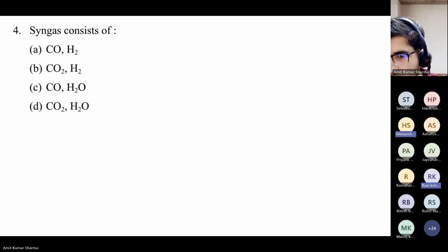Yeah, sorry to interrupt. In our industry, we are using a nickel-based catalyst for the reforming. Generally, the vendor says 5 to 6 years as the life of the catalyst, but it purely depends upon the gas quality and the temperature at which we are operating. So a lot of factors are there, but the vendor says it is 5 to 6 years.